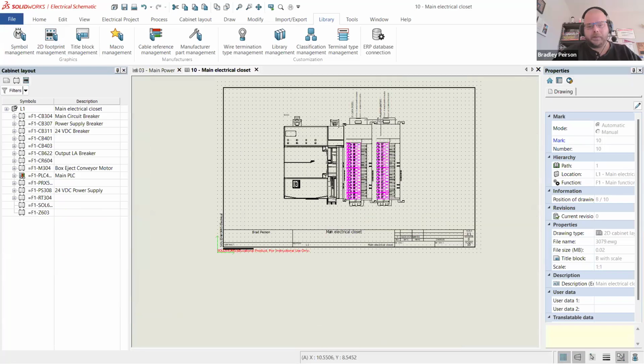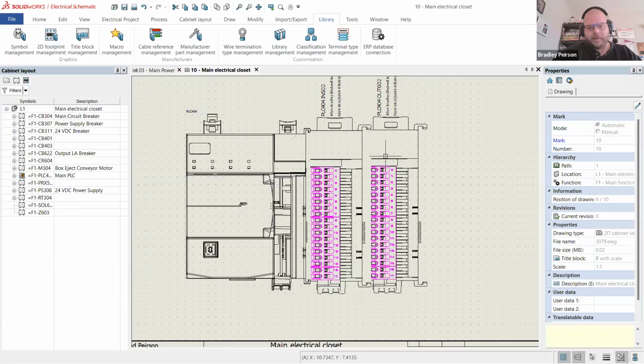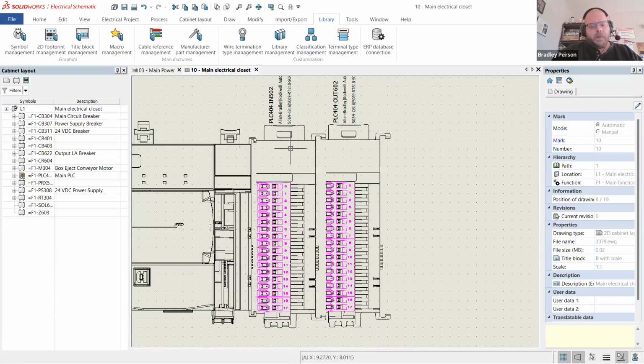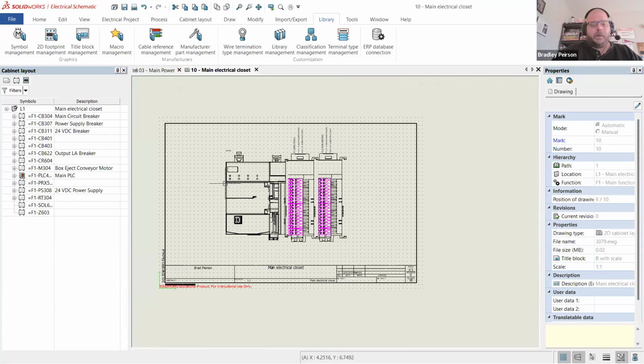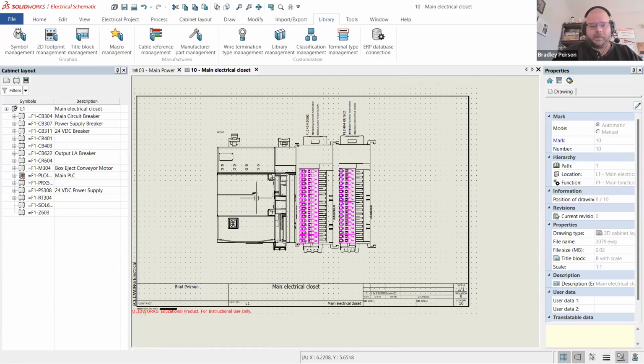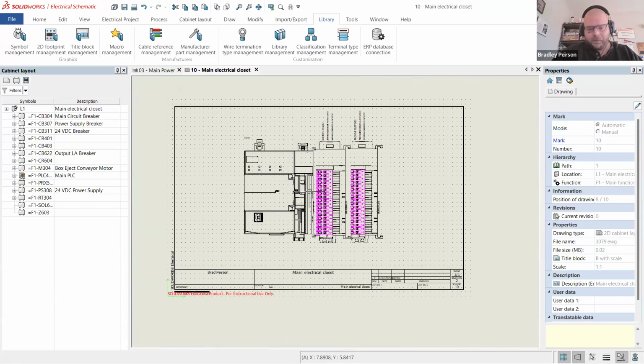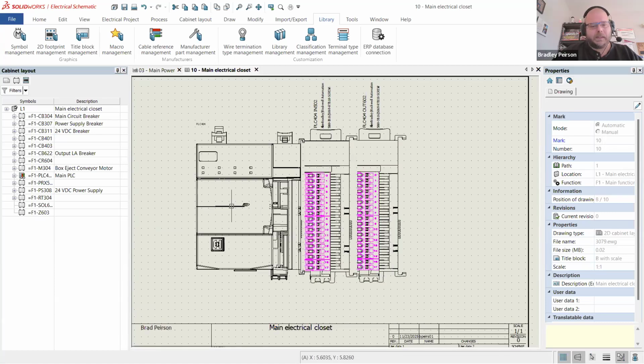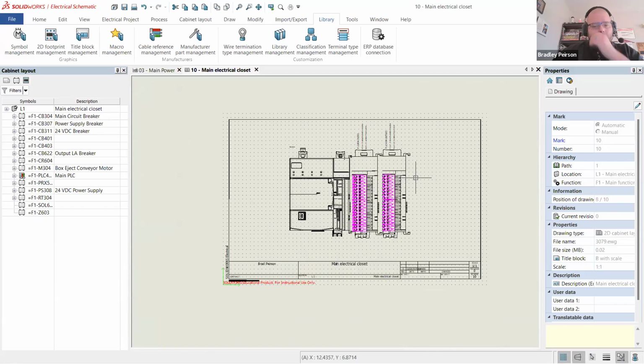But that's the thing to double check, because things are automatically scaled on our 2D footprints as we create these. We can also tell these clips should be the same size. We want things to be scaled properly because we're going to be dimensioning this thing and telling our technicians that are building it, or even ourselves down the road, right? We got to remember we're going to be putting dimensions on this. And if this is way off, it's going to throw everything else down the chain off. For now, I'm going to leave it alone, but that's a thing I'll need to double check, why that's so big.